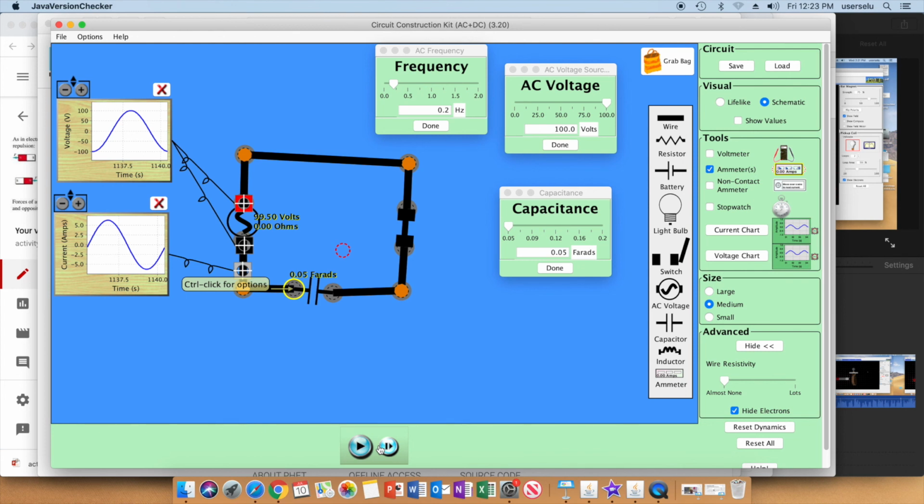And if we think of the cycle of a wave as going from 0 to 360 degrees all the way around one time for each wave, then 1/4 of a wave is what we call 90 degrees. So in conclusion, the capacitor is 90 degrees out of phase for its current compared to its voltage. We say that the current of the capacitor leads the voltage by 90 degrees. That's how it is described by electronics engineers. The current leads the voltage by 90 degrees.